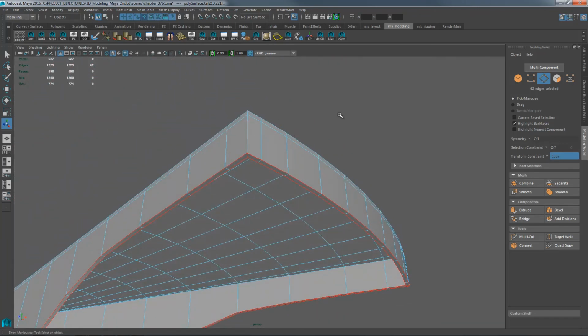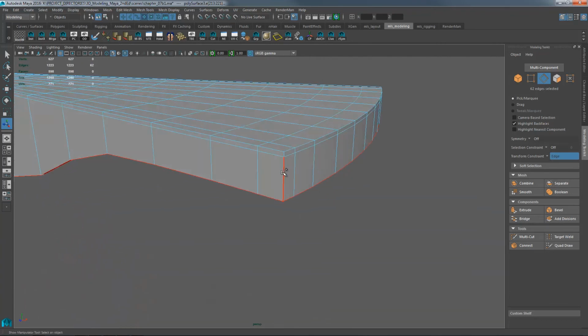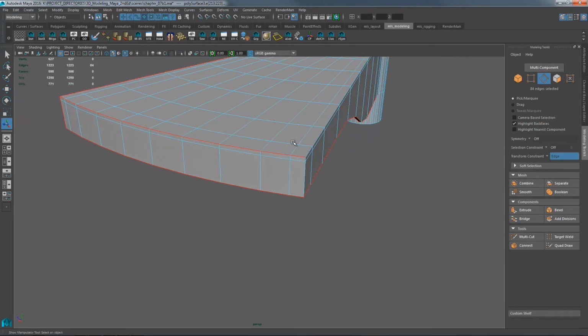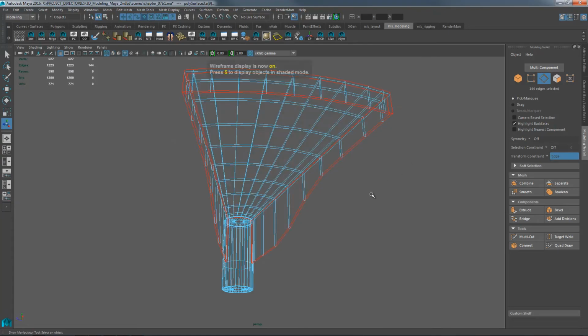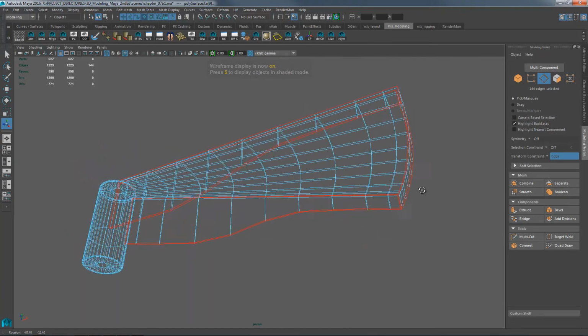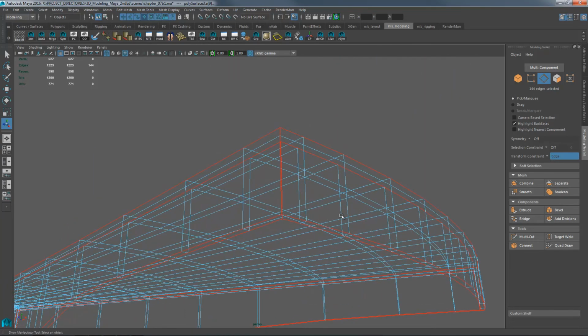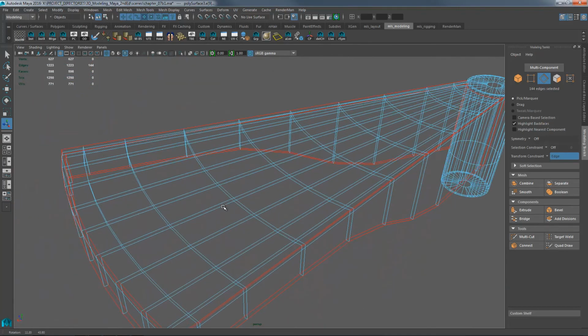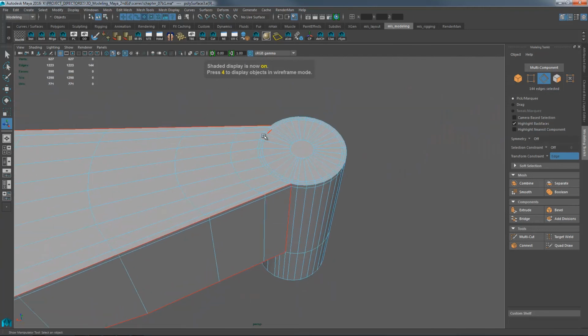And we're going to perform a bevel. Continue adding edges to your selection. Okay, here's my selection. It's basically the perimeter of the entire step, including corner cross edges. And I did not add this top part here where cylinder and step meet.